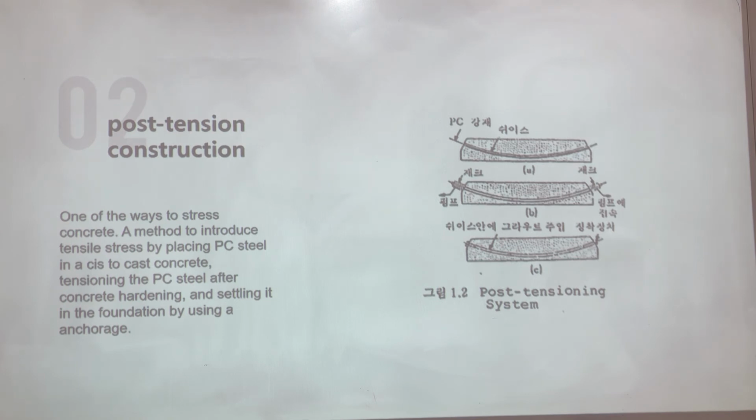The order of this technique is wire processing, fixing of fixed fittings, installation of steel wire, installation of supporting reinforcement, installation of steel wires, and installation of reinforcement bars at anchorage. Now I will explain the pros and cons of this technique.